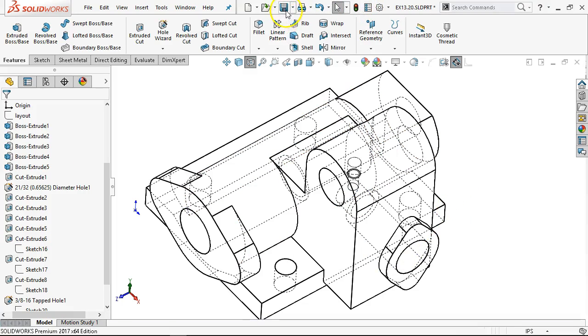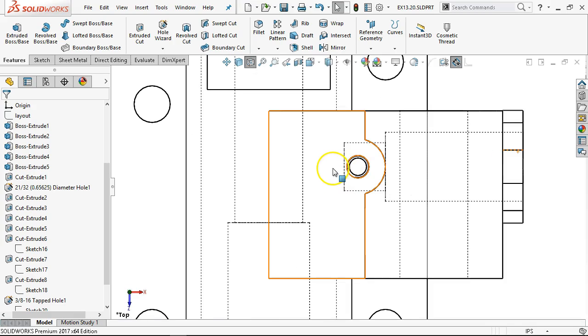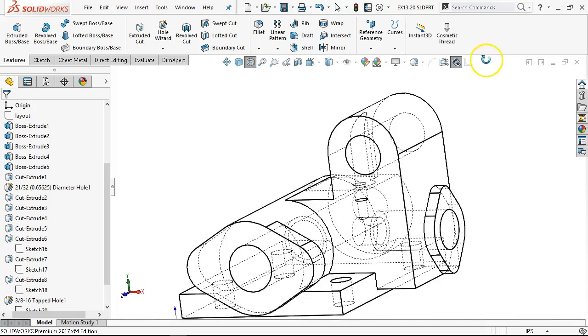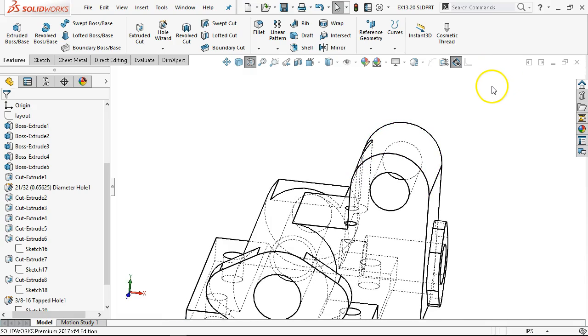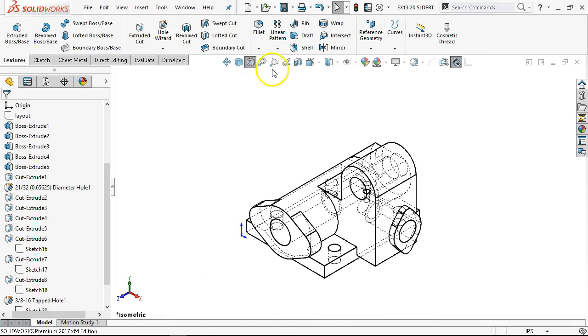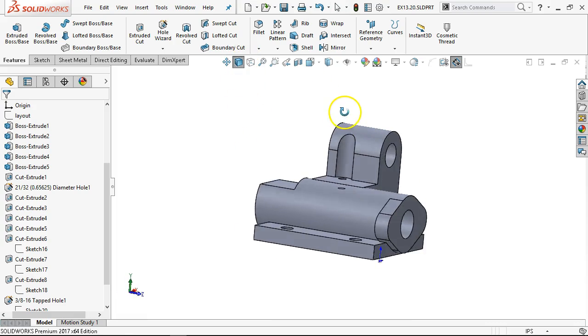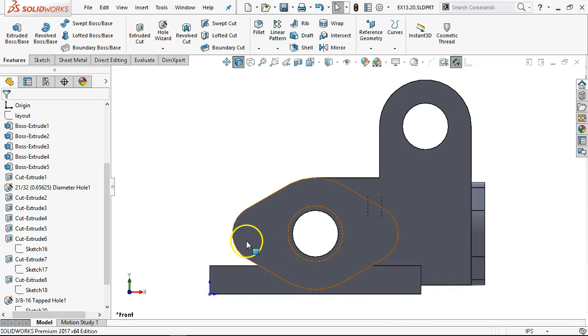Alright, so this kind of shifted into design mode as to what is going to make the fix. If we were on a drill point as opposed to a flat bottom, 3 inches to the shoulder would probably intersect it enough at the point, depending on what the 3/8 is actually doing. If it's a port for fluid, then that's different than it being a set screw for retention. Alright, so let's try and get this wrapped up.